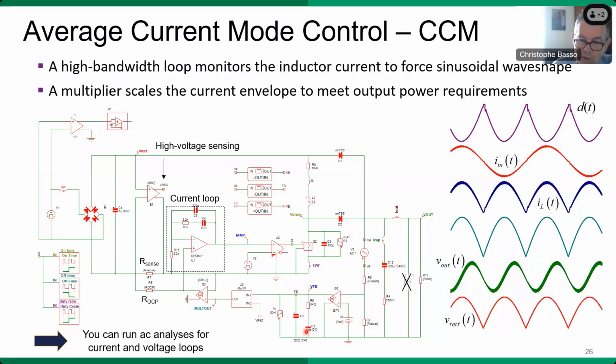And we can show, mathematically speaking, that the small signal response of the power stage includes the contribution of the square input voltage, so the square VAC. So it means that at low line and high line, if there are no compensation schemes inside the circuit, the crossover frequency will change. That's why you saw in an integrated circuit like the UC1854 years ago, they did include a divide by Vin square for compensating this power stage AC response and to make it independent from the input line.